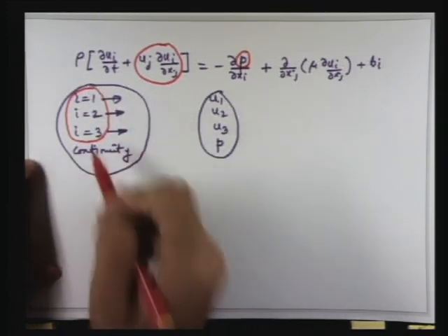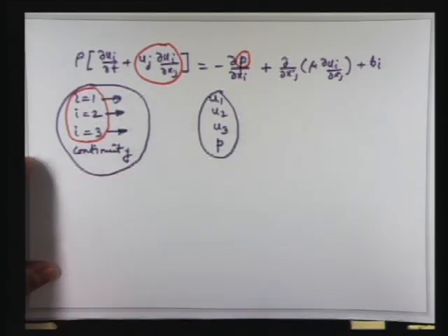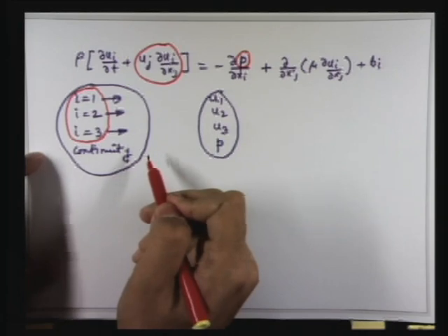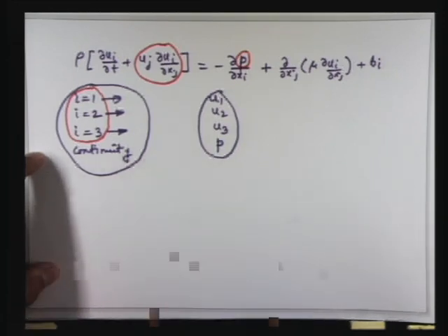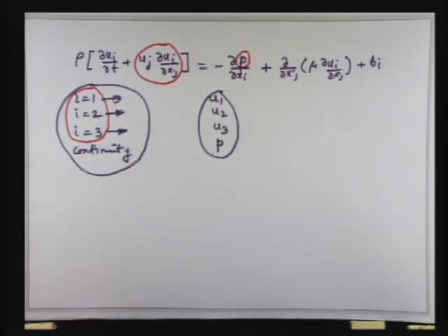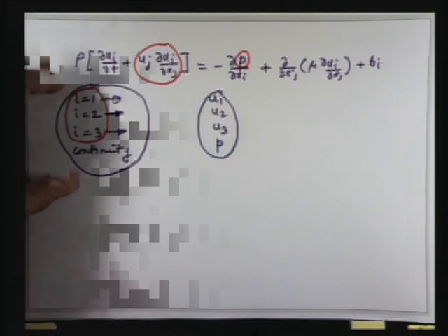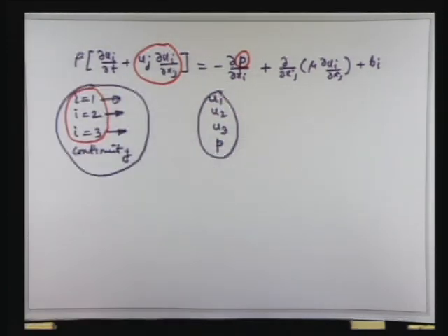Continuity equation is for conservation of mass, but you can link this with the pressure, and that gives additional equations. This is called the primitive variable approach. And then using that additional equation, you have governing equations for velocity and governing equations for pressure. You can solve that, and that is one of the ways in which modern CFD solves the Navier-Stokes equation numerically.